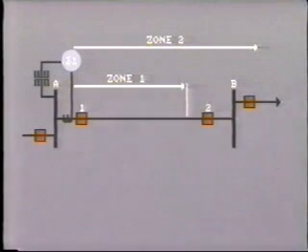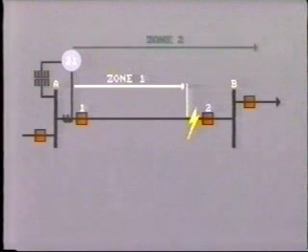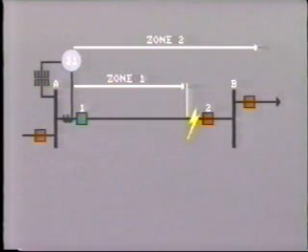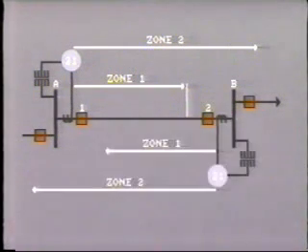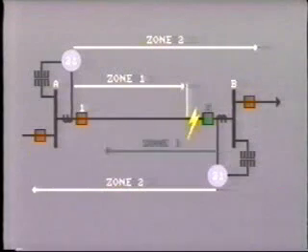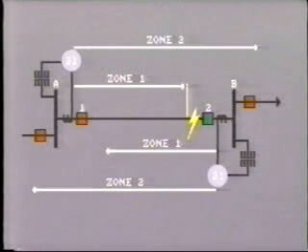Now let's turn our attention to line protection. We have discussed in earlier tapes the problem in trying to obtain 100% high-speed protection of the line. For example, with the distance relay, the high-speed first zone element is normally set to cover about 80% of the line. If a fault occurs within the remaining 20% of the line, then the breaker will trip on the second zone, but this will be time delayed. Even with distance relays at both ends of the line, the problem persists. In this instance, breaker 2 trips at high speed on the zone 1 element of the number 2 distance relay, but the clearing of breaker number 1 still has to wait until the zone 2 element at this bus has timed out.